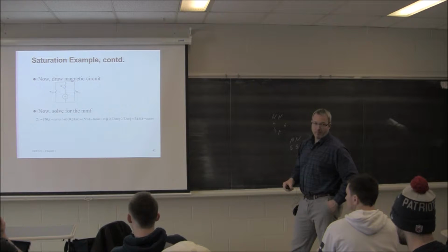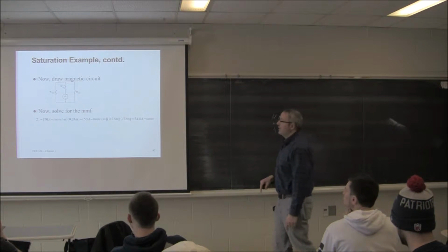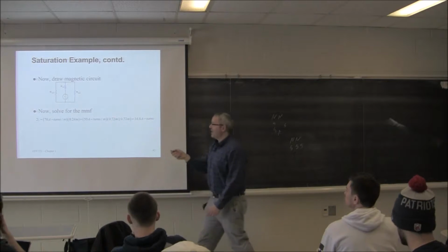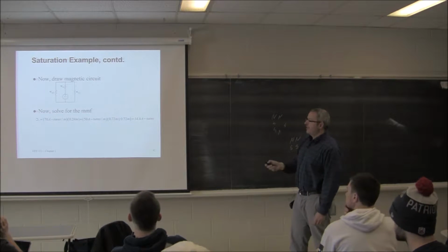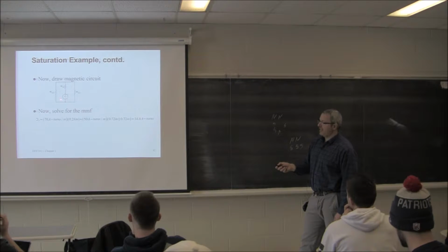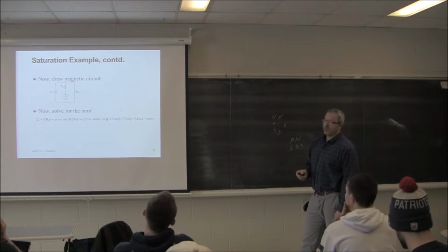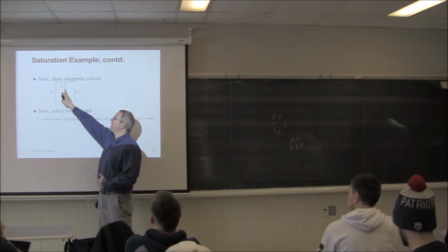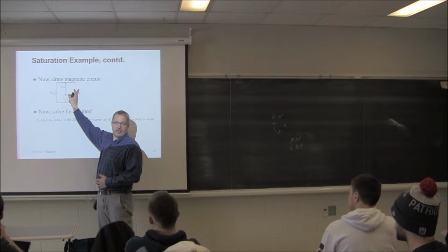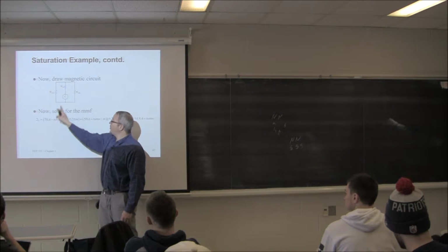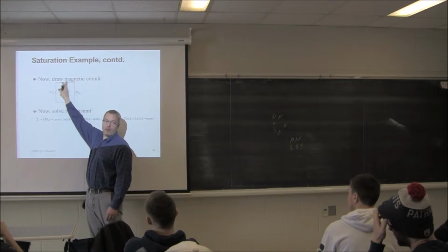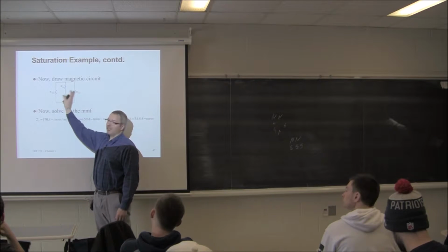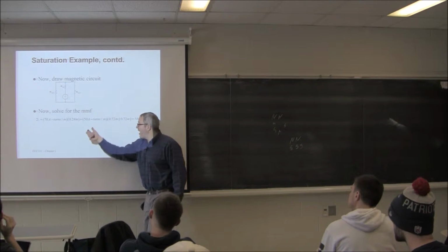The two outer legs, because they're in parallel, the current sort of dives off. Essentially what I'm doing is figuring out what the voltage source needs to be to deliver what is necessary to get those magnetic field intensities. So my MMF that I actually need to drive that magnetic field is 34.8 amp turns. So it's essentially trying to figure out what the voltage is here, because I've got to get this voltage drop plus these voltage drops. Does everybody see what I'm doing? This is the voltage drop here. I don't care about the voltage drop at this point. I want to know what this is minus the plus. So I need this voltage drop plus the voltage drop that's across those two reluctances. That's why I'm adding them up like that.